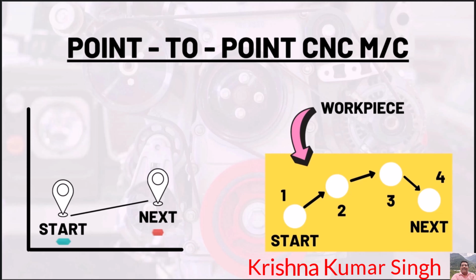So basically, a starting point and the next point is required for the process. Now for instance, if 4 holes are to be made, the program would simply specify 4 points in between the starting and next point, like 1, 2, 3 and 4 as shown in the figure, and the machine tool will perform the requisite drilling operation.